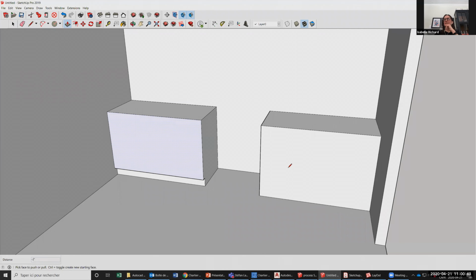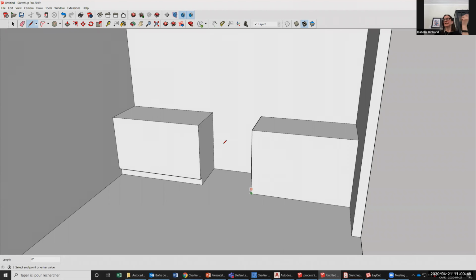I want to mimic the same thing, do the same thing here. I start here. Let's say I'm not sure how high it was at the beginning, the one here. So what I'll do is that I'll force the direction from down to up, and then just go towards the end of this segment here. So see, the line that I just created is exactly the same height as this part here, because I indicated while forcing the direction to have the same height.